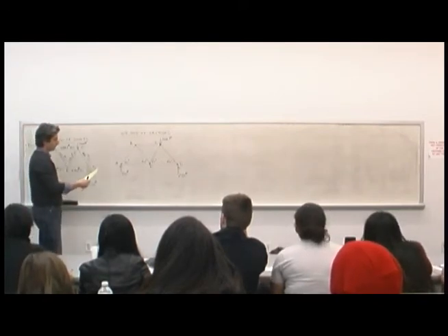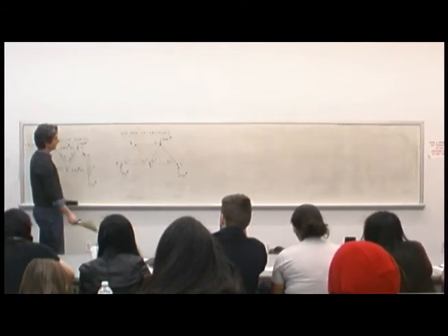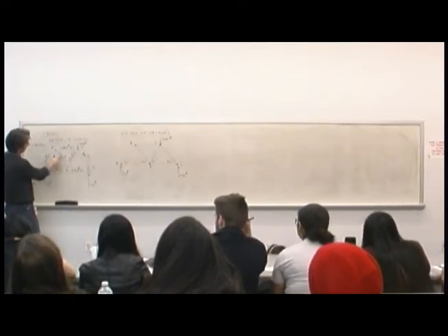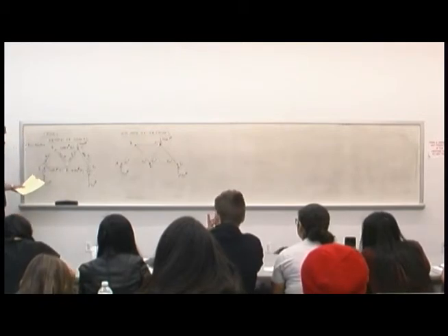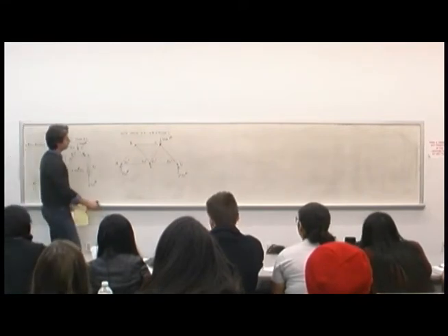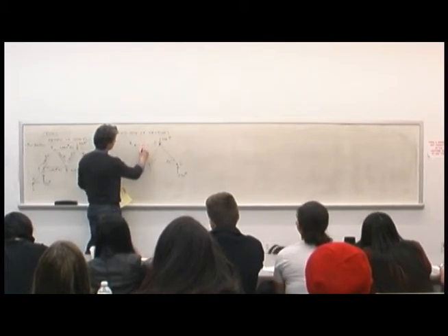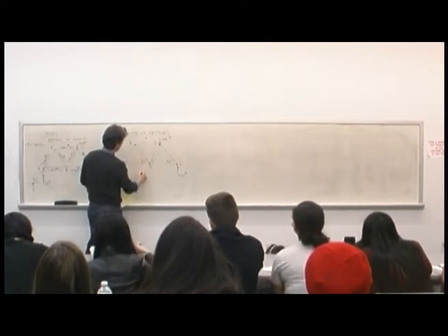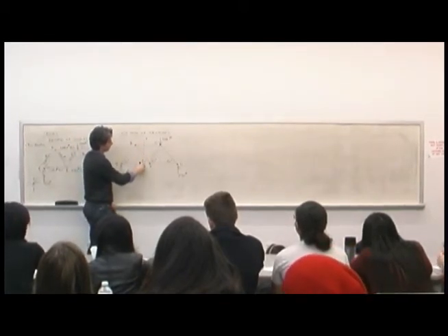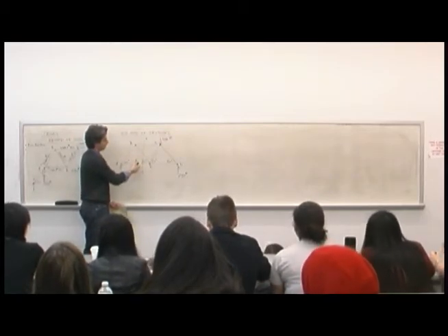So let's see, what do I want to solve for? Let's solve for BE. Okay, so this diagonal here, by method of joints, we found it out to be 288.7. So I can take any section I want. I imagine cutting through the member or the structure. So if I cut through, what happens? I'm cutting through this member, and this member. And by doing that, you want to think of exposing the forces in that member.